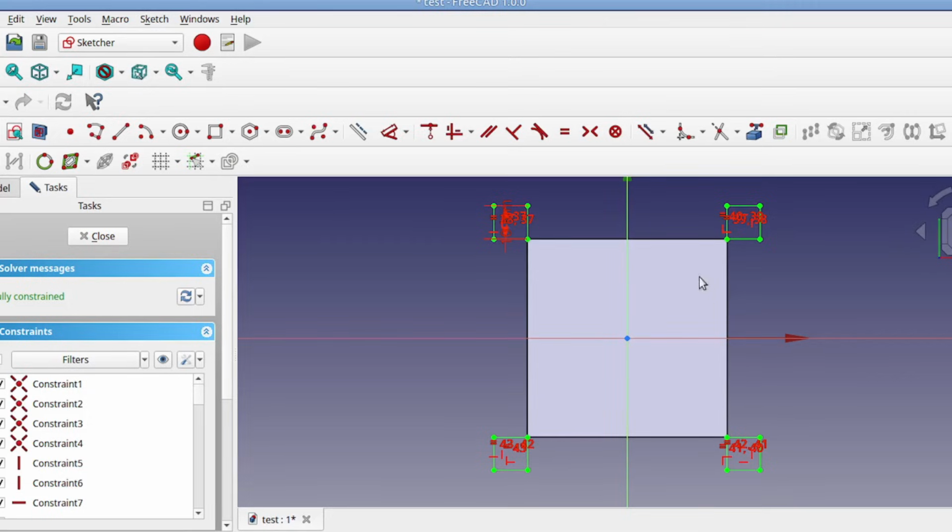When this inner box shrunk down beyond their dimension, when it came down beyond the outer corner, they flipped around. And that can really screw up your geometry, especially if you have something with B-splines or curves or arcs. The arcs will turn inside out, and it can be quite a mess.